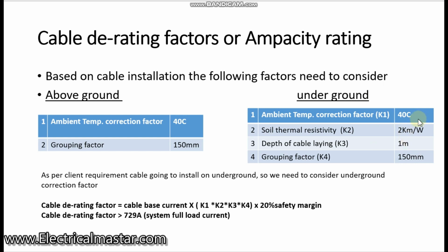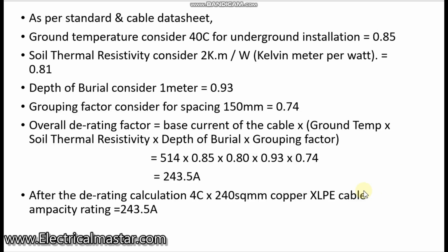So we know these details, but we don't know the values for these details, like soil thermal resistivity and grouping. These values you have to refer only from the datasheet of the manufacturer of the cable you are choosing, not the IEC standard. From the IEC standard you only consider these conditions. The particular values you have to check in the manufacturer datasheet.